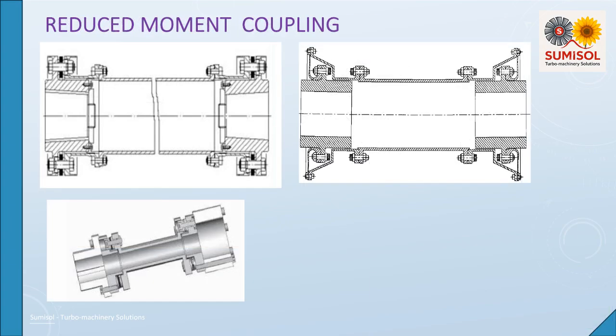Reduced moment or close-coupled couplings are high-performance, specialized drive components used in high-speed machinery, like turbo compressors and pumps, to minimize overhung mass and journal loading, reduce bending moments, and handle misalignment.